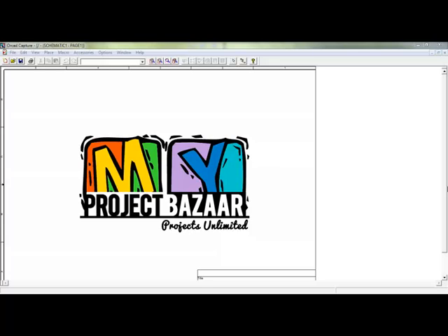Now we simulate this by clicking the setup simulation and selecting the transient or Fourier analysis to choose the timing limitations of our output waveform. Here I choose 100 nanoseconds, and 10 nanoseconds for step size. Then click the run option to start the running operation and extract the waveform structure of our proposed work.